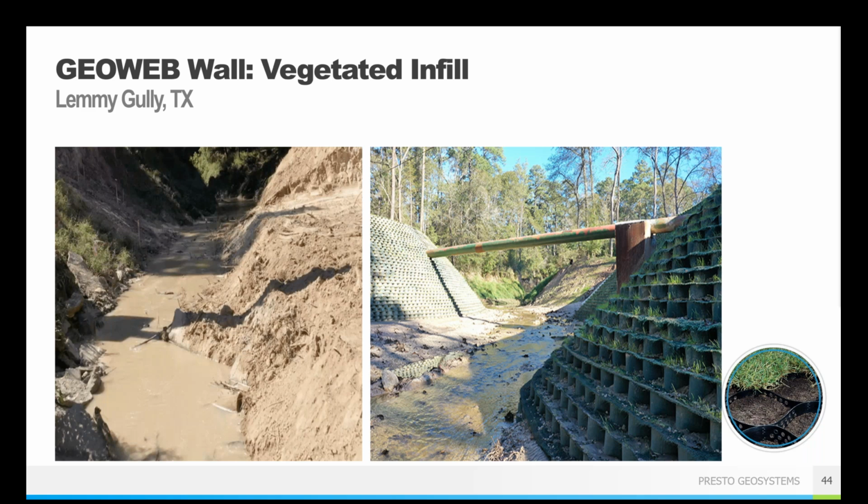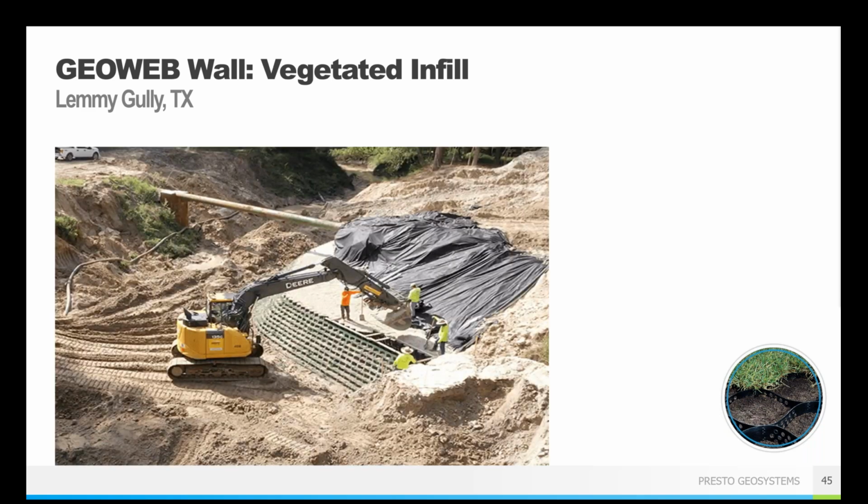In this case, they did block off all water flow through the gully because they wanted to work in dry conditions. You can work in the wet with the GeoWeb system as long as your contractors are comfortable with that. That's absolutely just an installation comfortability thing, dry or wet. So don't think it has to be dry if you're not capable of doing dewatering for your site.